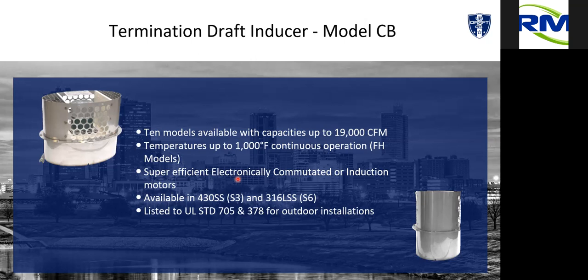EC and induction motors. So we offer it in 2 different styles, stainless. All of our fans are available in 316L. The reason we do that is because that is a more robust metal to handle condensing applications. And again, UL 705 and 378.